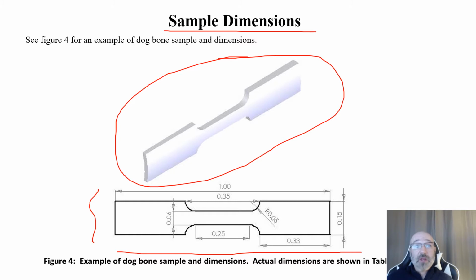Now, something to think about here: when you're machining these out in SolidWorks, you're basically saying, this is the shape, go ahead, do a cutout or an extrude around it, whatever it may be that you're using for your process. When you do that cutout, it doesn't really take into account the diameter of the cutting bit that we use, the 3/32 one that we specified there. So we do really want to consider whether you can fit that bit in there with the physical shape and dimensions of the case as well.